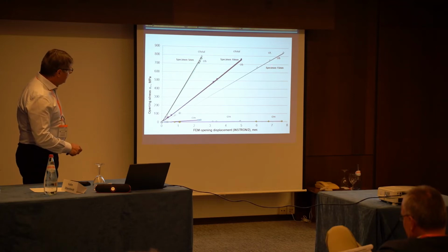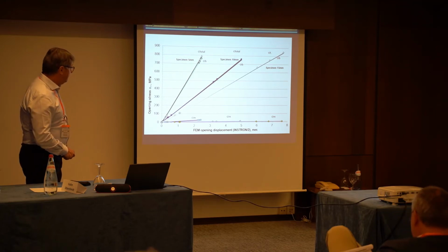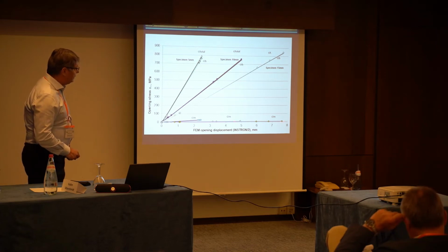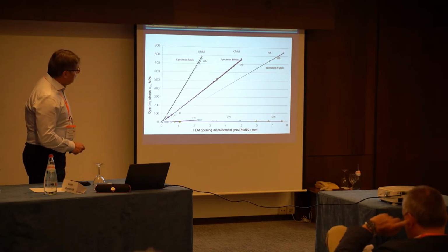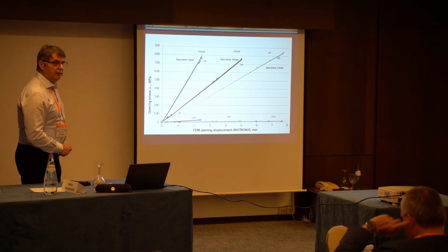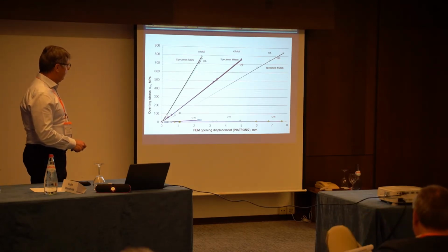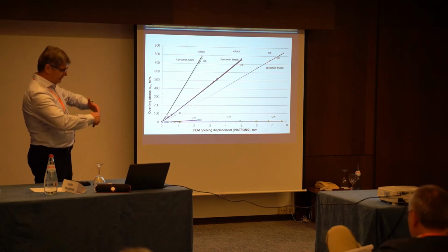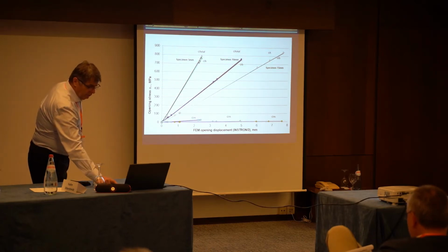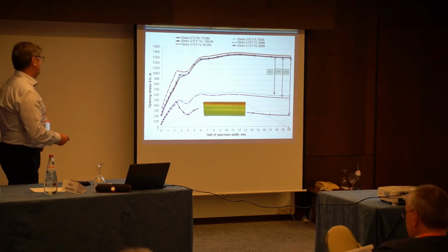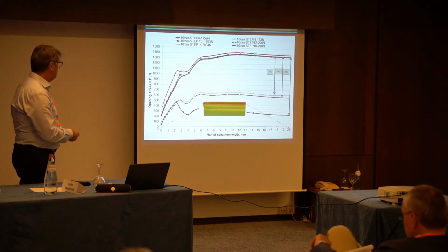And also you can see that, for example, for these 50 millimeters, the membrane stress is almost constant, a little bit more than 0, and it is mainly just the bending stress, which is contributed by displacement.